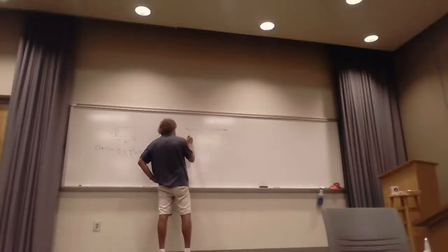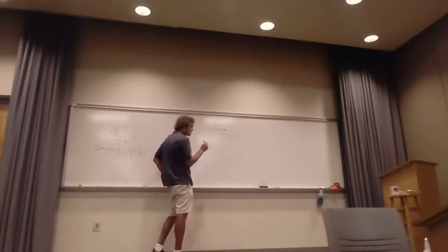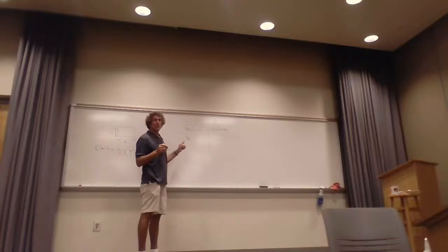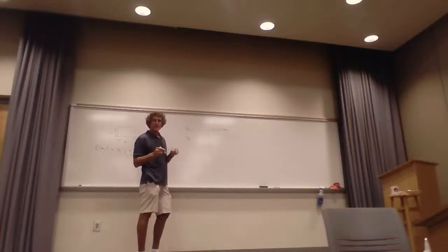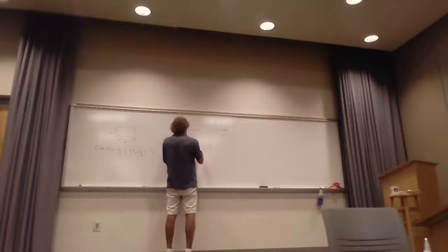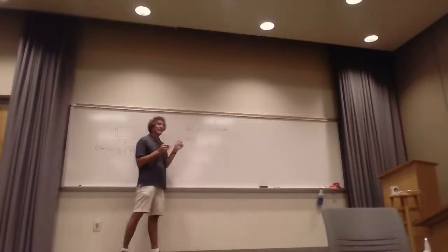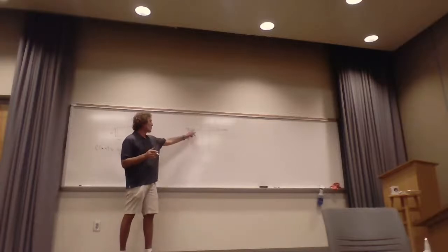Then the next frequency, this is a little odd because usually it's 10, 20, and then 01. This next frequency is the 01, isn't it? Because you have to go through it. So it's TE01. Remember, it can't be TM because TM requires both of these to be greater than 0.